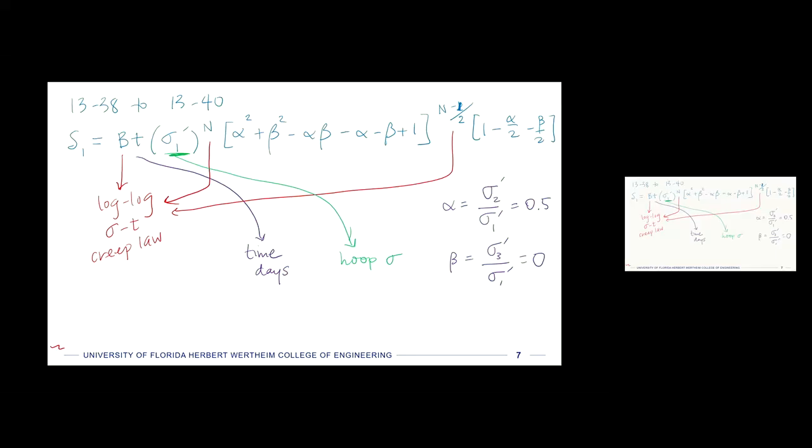So you can see now that if we have a limiting shear strain here that had to be 0.03 or less, then the only thing we don't really have is that thickness in the hoop stress. That's the only remaining variable here. So we will basically just plug everything else in and solve for that.